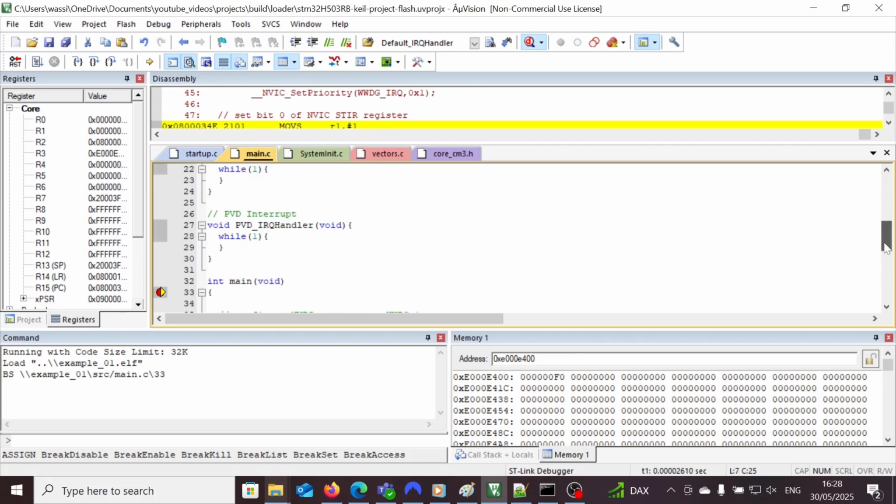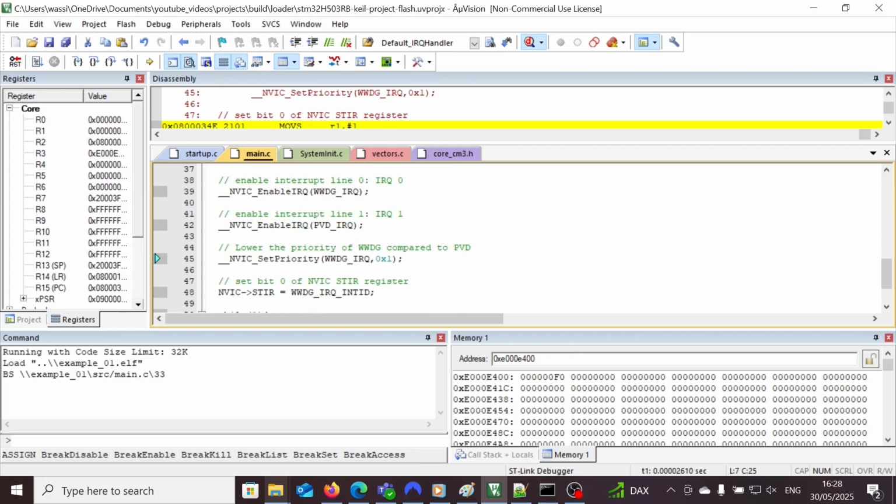If we say 1, then it tries to write to those 4 MSB bits, not to here. If we specify 2, then it knows where to put 2, here, not here, and so on. With this easy trick, we can recognize our split point to determine how many bits are used to define the different priority levels within our ARM Cortex-M microprocessor.